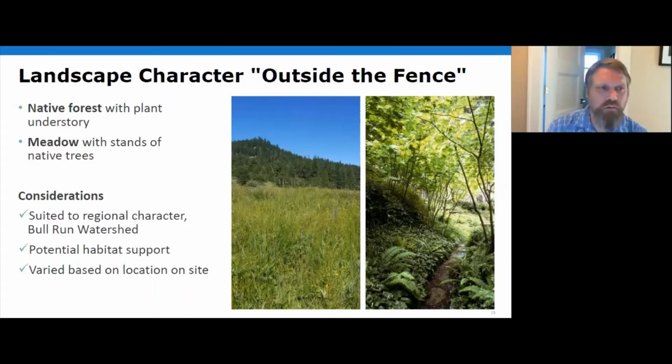So we're aware that's another drainage pattern on the site, and that's another thing we'll be aware of. And just to reiterate, the strategy we want to take is to try to keep the stormwater on our site to match the existing conditions, and not modify the amount that is leaving the site at any one time. So try to match the existing condition as best possible.